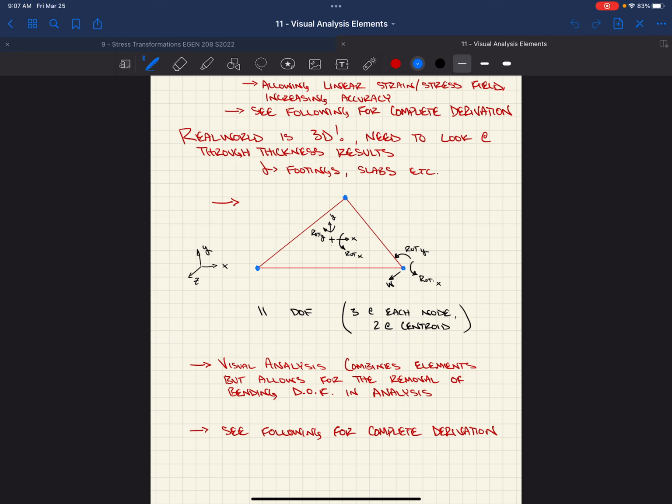You're going to have shape functions that allow us to take out of plane loading, like loading in the z direction, and split it up to our nodes, which would then create out of plane displacements, rotations in x and y, rotations of the entire element itself. And so if there's a decoupling, you could essentially have through thickness behavior or in plane behavior or a combination of the 2.